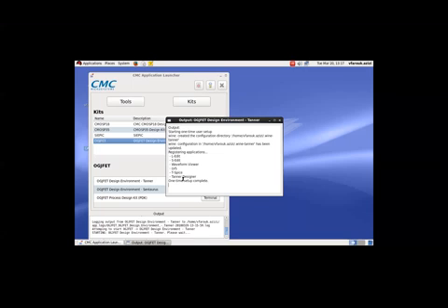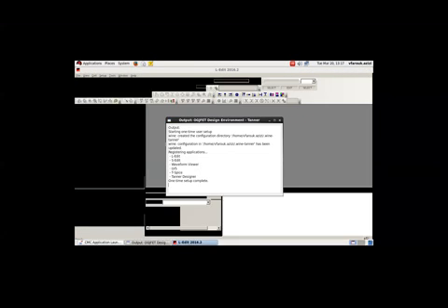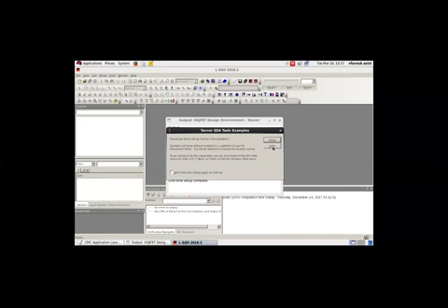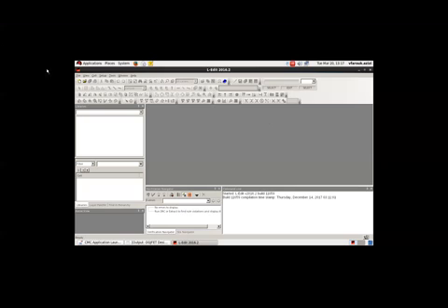Okay, so let's go up. So once we have our L-Edit running, you will need to find the design file, which will define and create your design environment, which includes the design rules along with the dimensions that you can use for your device.